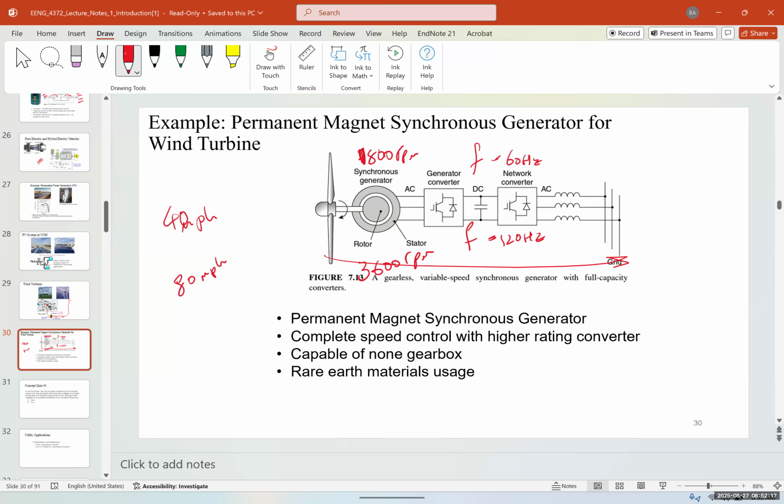of the blade. If you pass a wind turbine on a windy day and you see it's just still, it doesn't move, it's because the grid is getting too much power and we have to shut down the turbine. How would you do that? The blades actually move and you put them perpendicular to the wind and it stops moving, or you can reduce the speed. Sometimes you can increase the speed, so you move the pitch and the yaw. You can make it perpendicular, both the wind turbine itself and the blade itself. Both of them move.